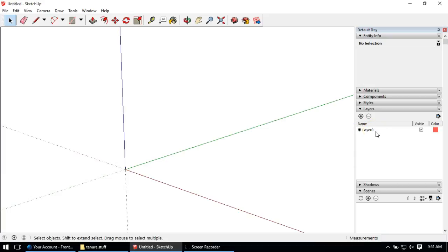There's reasons for that. I'm not going to get into it in this video, but highly recommended that all your drawing generally is on layer 0. Now, I'm going to make an exception for this, which is we have 2 drawings at the end of this that we're going to have to make, which has notes. Two views are going to want to have notes. And they're going to want different notes. So I'm going to make text 1 for my first group of notes. I'm going to make another layer and call it text 2 for my second group. And then I can toggle these on and off, because generally in many ways they work very similar to AutoCAD. But this is all I'm going to need to do.